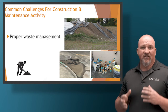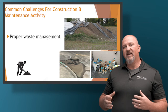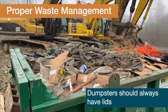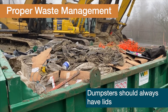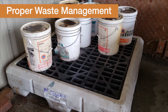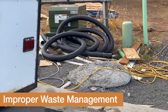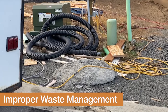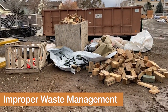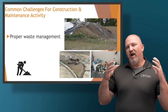Waste management is also very critical on our projects in terms of how we manage our site. Even your support vendors can leave half-used buckets of materials out into the weather and rain fills them up and introduces pollutants to the stormwater, and we need to control that. We need to make sure that we've got management plans for all of our waste products. You need to have proper disposal processes in place and use dumpsters with lids on our projects as well whenever possible.